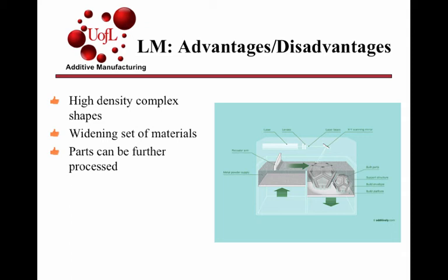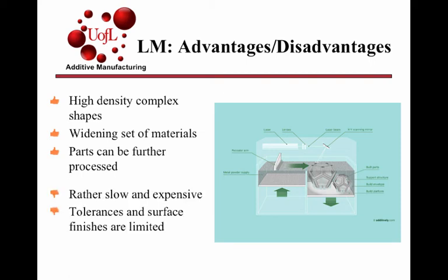Typically the mechanical properties you can get from SLS are greater than you can get with fused deposition modeling. Because you have to use fine powder to be able to get good features, you have to work with something that is very slow.